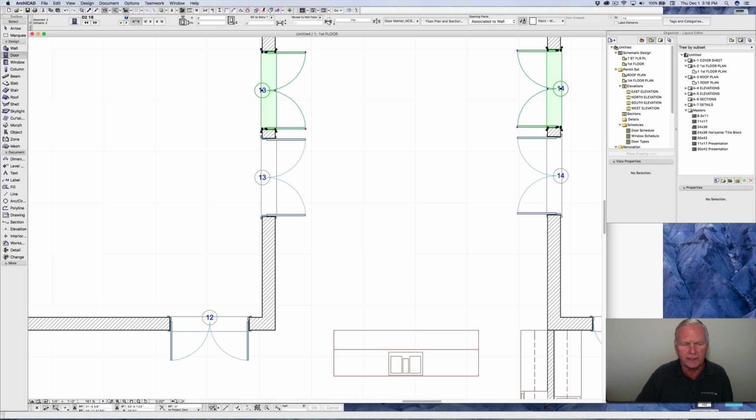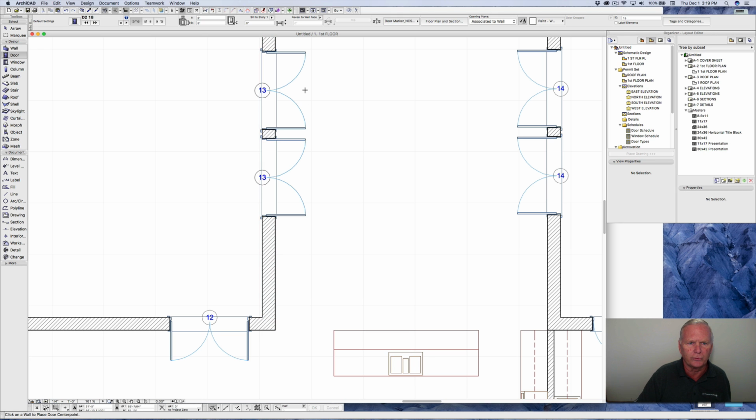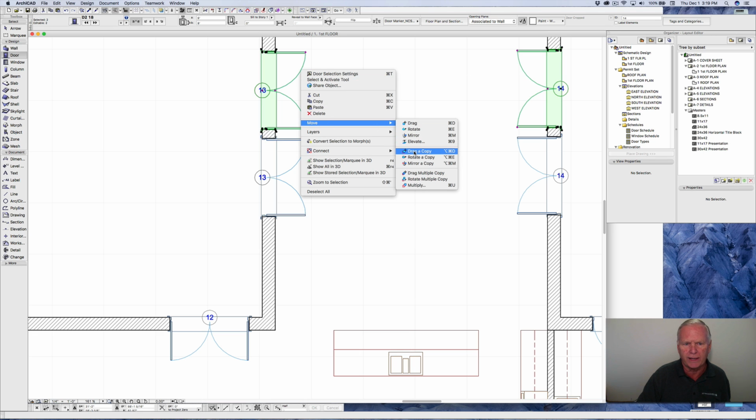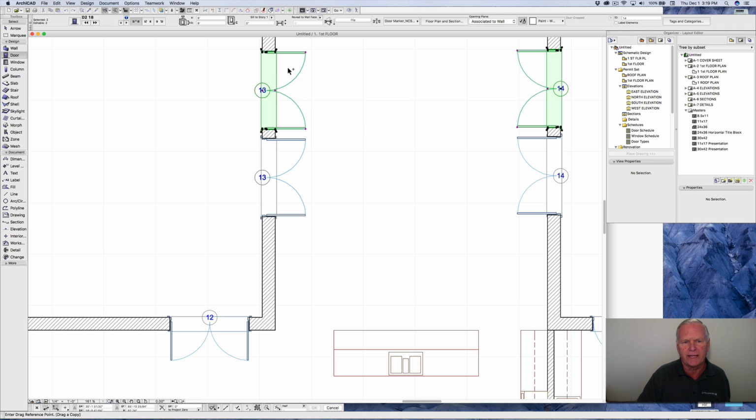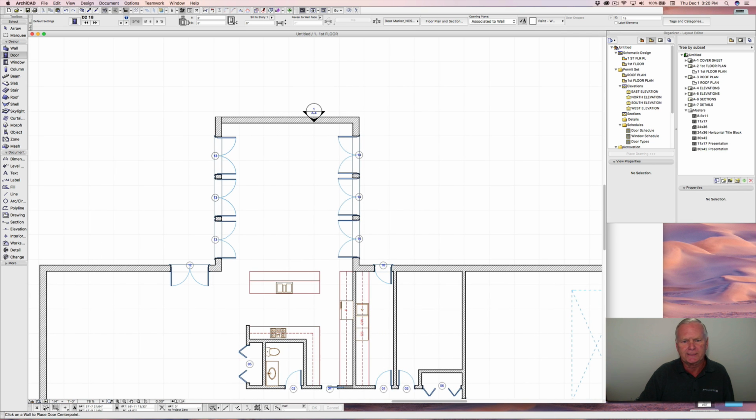Now without clicking and just a little bit of thinking, we've got 6 foot 9.5, we went this way. Okay, so we're going to right click here, we're going to say move, drag a copy, and now we're going to drag, and what happened there was I actually highlighted the wall and we unhighlighted the 2 doors. So we're going to go back and click on both these doors, make them hot again, right click, move, drag a copy, and that 6 foot 9.5 going that way is double going the other way. Of course, is 13.7. So all we do is kind of drag in this fashion and do D13-7, hit enter, and we've got those set up, and we'll zoom out a little bit, take a look at that. Again, just a couple little tricks to make it speedy and equal.